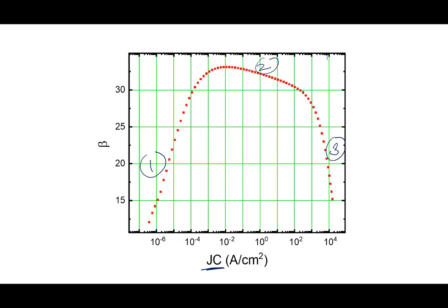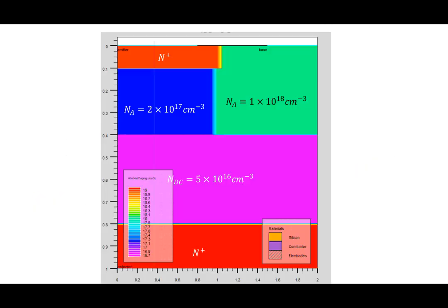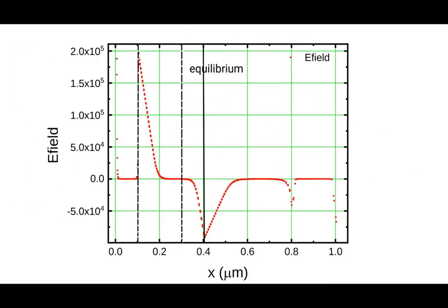Segment number 1 is primarily because of the base current, which we have said is made up of the following. Base current is normally because of holes which are going here. But there is also a base current that comes about because of recombination within the depletion region. We have discussed that in a diode, at low bias there is recombination within the depletion region, and at high bias, other things. Recombination within the depletion region goes as e to the power qV by 2kT.